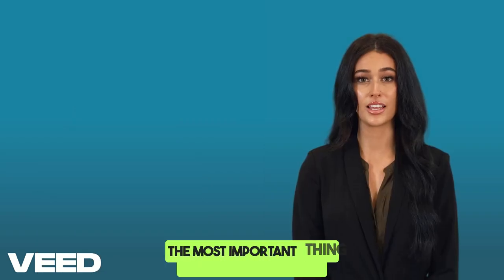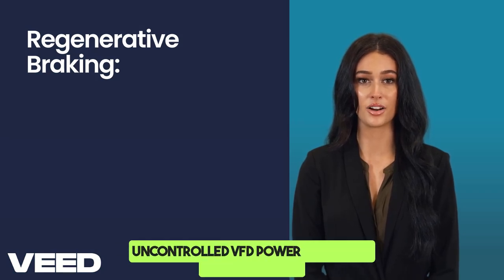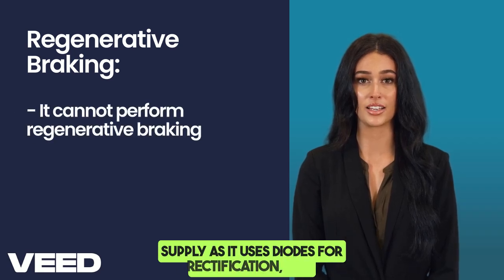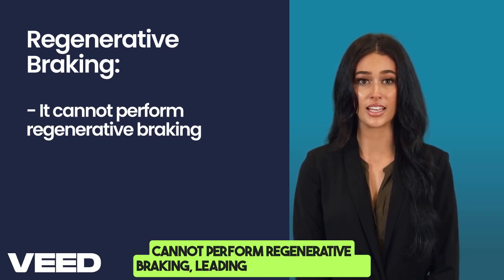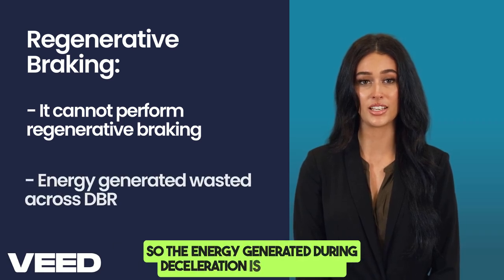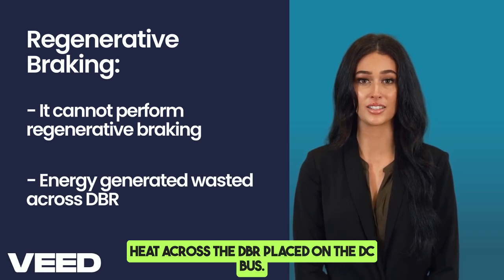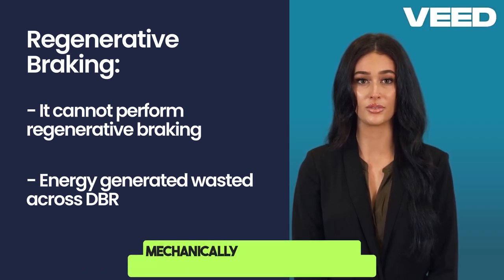The most important thing, regenerative braking. Let's see how both handle this. In an uncontrolled VFD, power cannot be fed back to the supply as it uses diodes for rectification, so it cannot perform regenerative braking, leading to energy losses. So the energy generated during deceleration is dissipated as heat across the DBR placed on the DC bus.